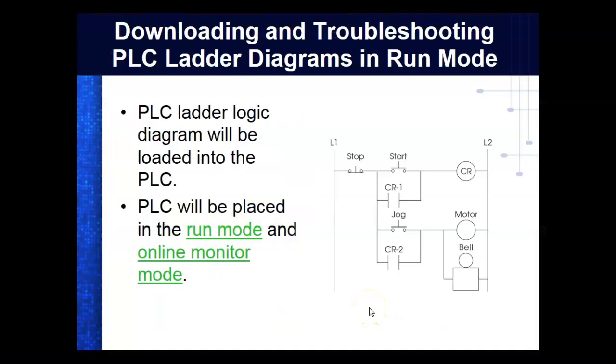So, by the way, in your book, they're going to call this CR1 and CR2. That's non-existent. They both get the same name because they're controlled by the same relay. So in your lab book, you need to just mark off that right there and just call it CR. So what we do is we just give the contacts controlled by these output devices the same name.